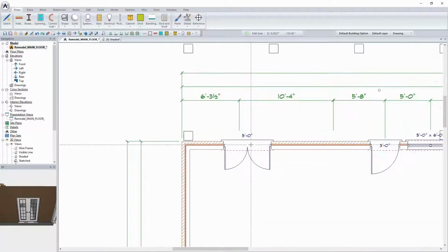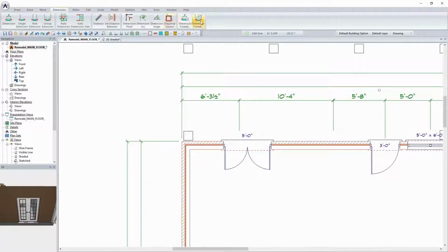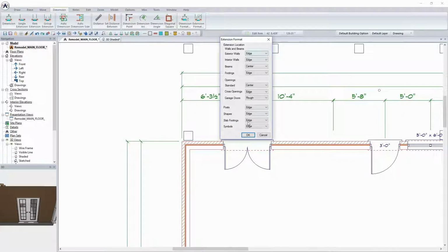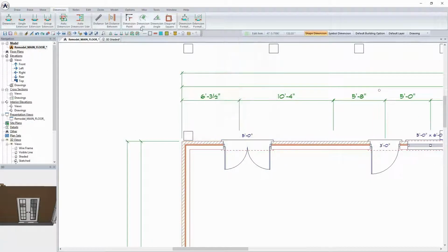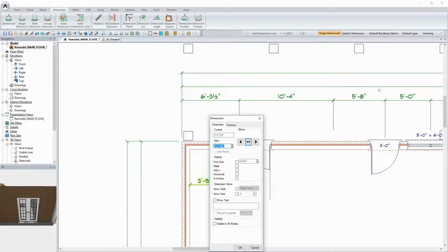Additionally, there will be some small windows that will go in, and we'll get to working on that. But the first thing I want to do is change my dimension and extension formats on openings. I'm going to change my openings to run to the edge at this stage so that when I pull my extension options off, and the interior dimension is more important here, I need to make sure I've left enough room for the kitchen cabinets and so on to go in there.